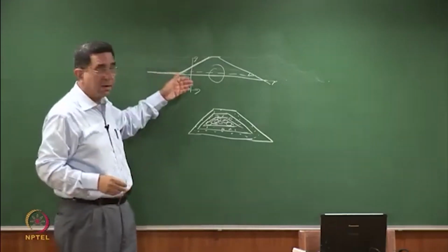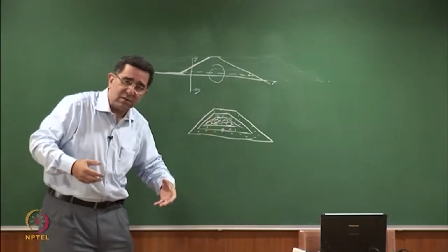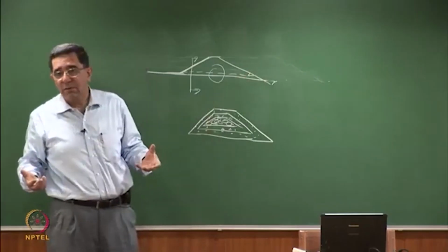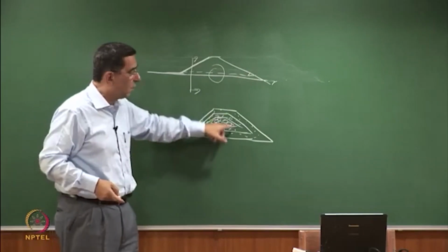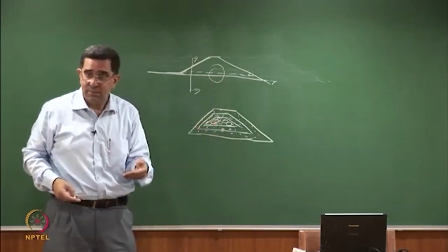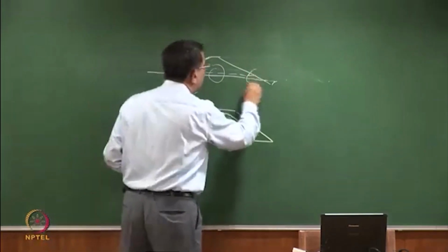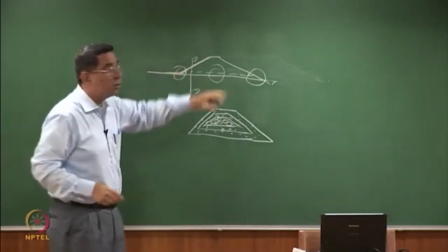Such a drain would allow your water to pass through it, and even if it settles a little bit, it's not going to crack. So these are all filters around it, such that the fine ash or the fine tailings don't come through it. And remember, you will need a rock toe here, and a filter here, and a toe there.